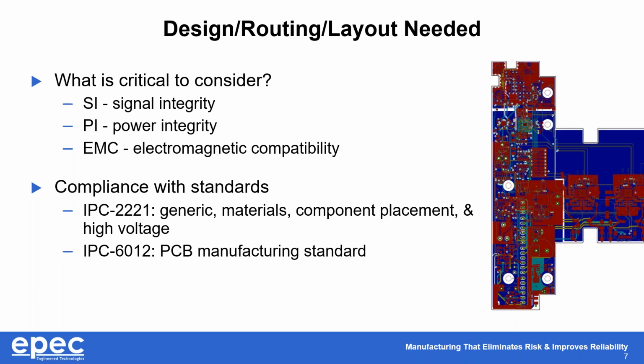Your compliance standards that are needed. IPC 2221 is your generic spec for all things component placement and high voltage. And IPC 6012 is your PCB manufacturing standard. That is what Epec uses to manufacture to. IPC 6012, the latest revision, Class 2 and Class 3. Class 2 is the most commonly used. Class 3 is an equivalent to military.